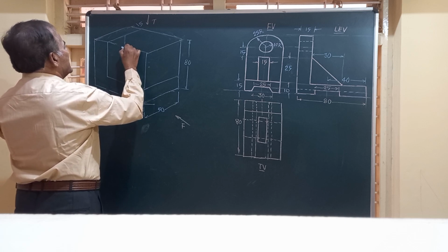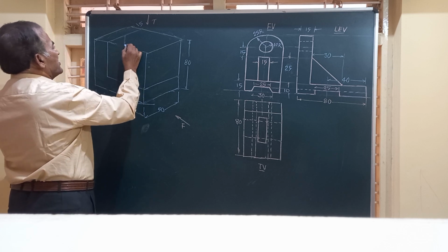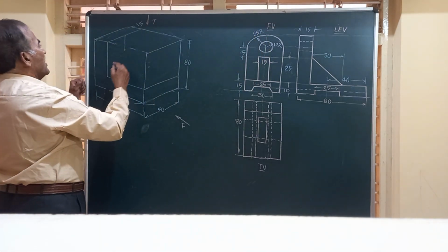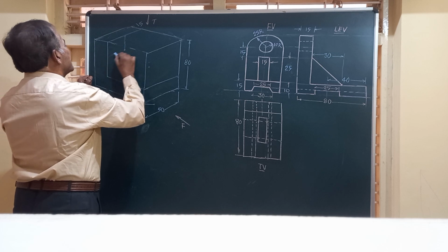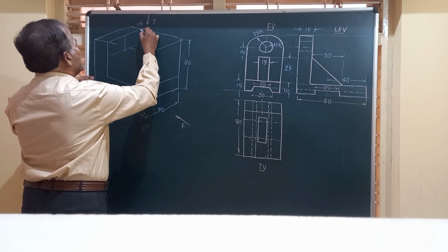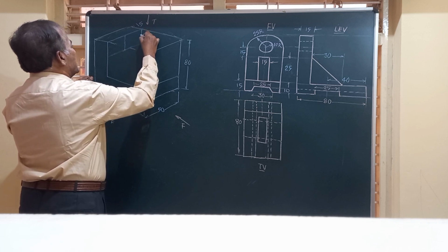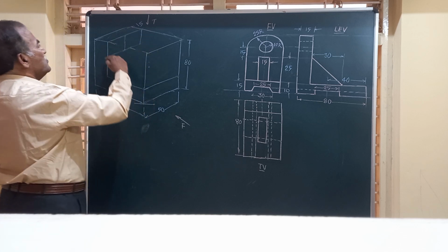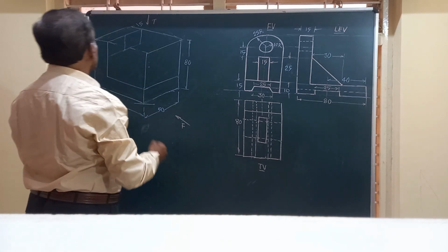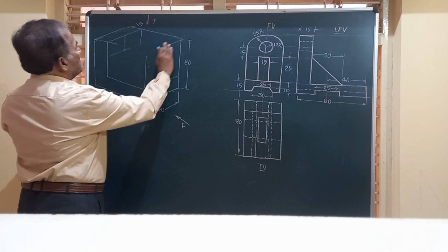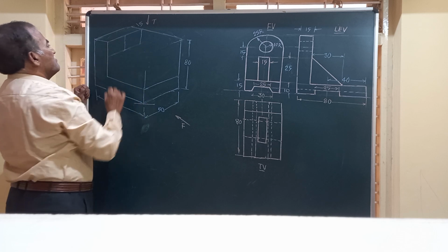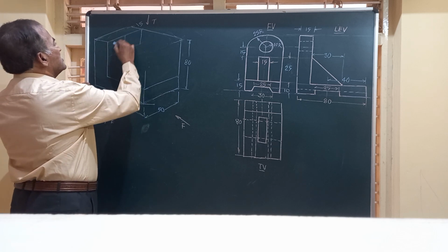We should take anywhere on this, say in the midline or here, exactly in the middle. I will take a distance of 15 millimeter. So say this is the center. So this is 25 height, sorry. This is 25 millimeter height. Here to here 25. And friends, let me have one more box constructed here, because in the end view, this semicircle appears as a semi-ellipse. So friends, here we are supposed to have that ellipse constructed. And friends, how to construct this ellipse is very important now. So what I do, I just make use of the four center method to construct an ellipse in this box.